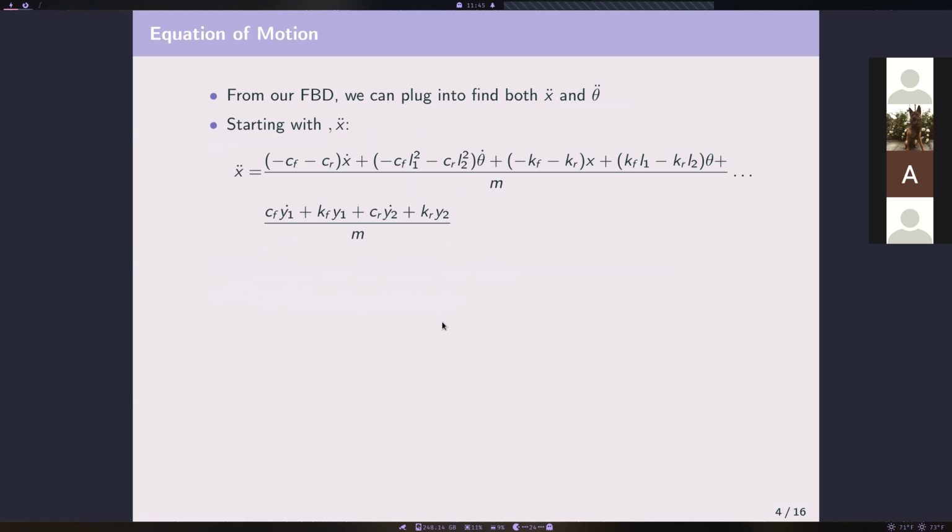Okay, so here we are. This is our first equation of motion for the coupled system that we have. So we have our linear portion here for the bounce amplitude. This coordinate that we have is x, but that's the car bouncing up and down. And then we're also going to have a coordinate of y, and that'll be our tires going up and down on the road. So we have the car itself going up and down, that'll be x, and then we have y, which is basically from the sinusoidal road profile, and that'll be our tires going up and down. So this will make a bit more sense once we start modeling inside of MATLAB.